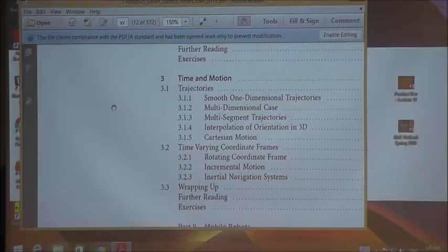You need to know the meaning of kinematics, forward kinematics, and inverse kinematics. It is much more challenging, as you know, to deal with inverse kinematics than forward kinematics. One has a straightforward response with an answer right away. You just change 6 angles and you see where you end up. That's forward kinematics. And the other one is very difficult because you are given where you want to be.